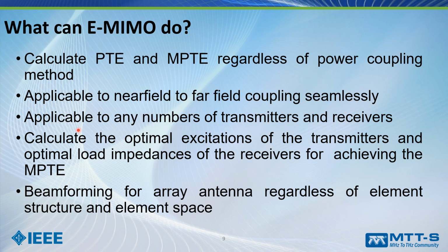It is applicable to any number of transmitters and receivers, and it can be used to calculate the optimal excitation of the transmitters and also the optimal load impedance of the receivers for achieving the maximum power transfer efficiency. Further, it can also be used for beamforming of array antennas regardless of the element structure and element spacing.